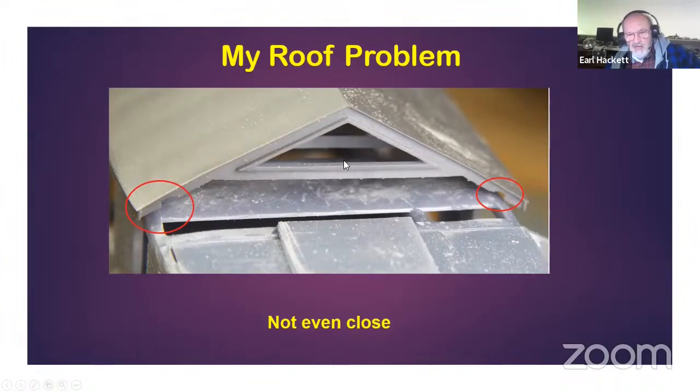So this surface is getting not only the incident light it's supposed to get, it's also getting reflected light from the opposite surface. So this surface underneath here got a little more energy than this one, because here the light would come down and just bounce off and go away. And so this lower surface shrunk. And you can see it's not even close to fitting on the building.